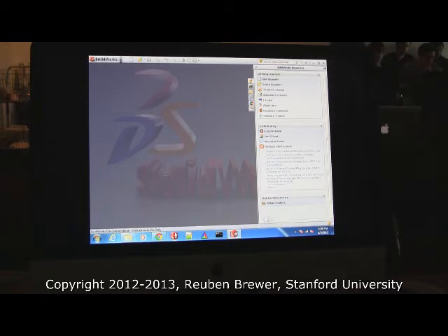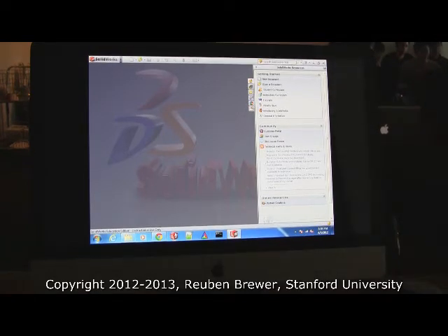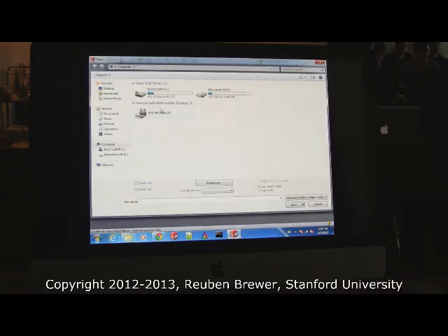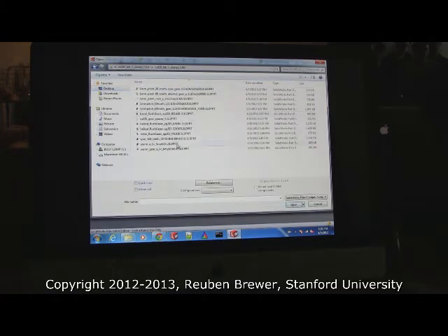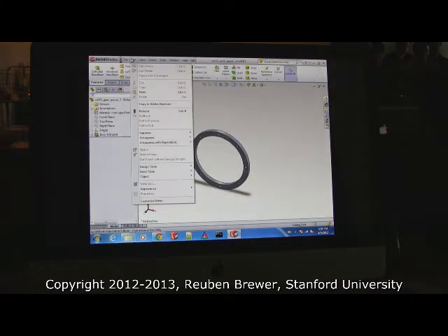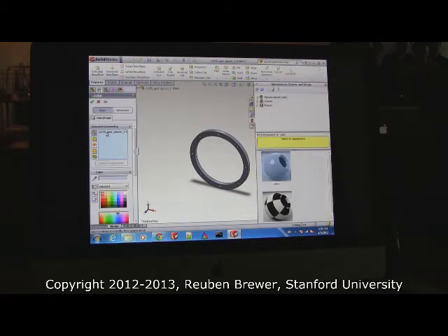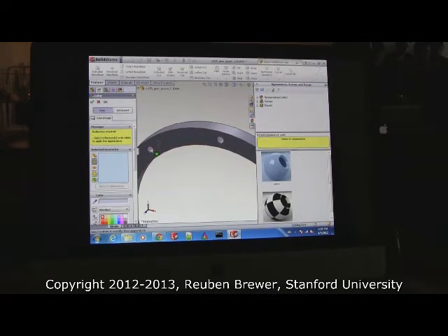When you're changing appearances, you have to first select what type of thing you're going to select, like a surface or a feature or a body, and then click the part. So go to that list, delete the name of the thing, and when you've done that, select surface. Okay, face, sorry, the second one, select face. Now zoom in and select one of the smaller holes.